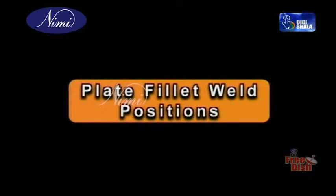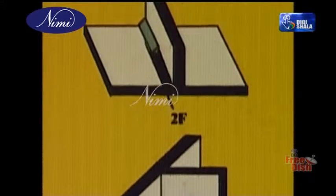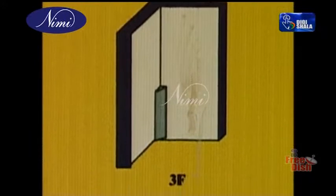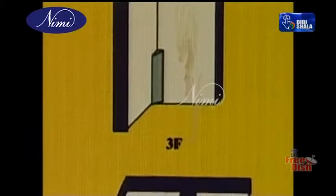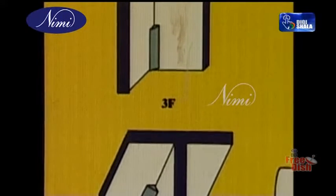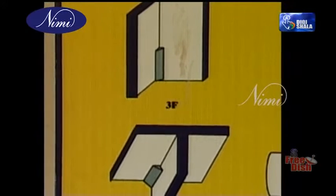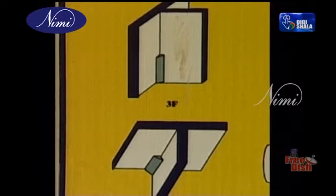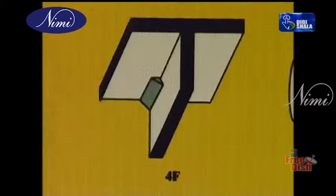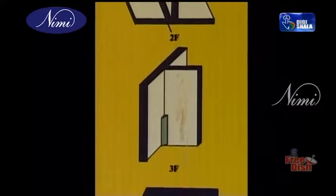Plate fillet weld position. Now let us study the welder's qualifications. This is very important because unlike other trades, here the welder has to be qualified according to the international standards. The basic requirement for the welder is to start with a fillet weld qualification. These 4 positions, that is 1F, 2F, 3F, 4F, are the easiest and the simplest of all to start welding.